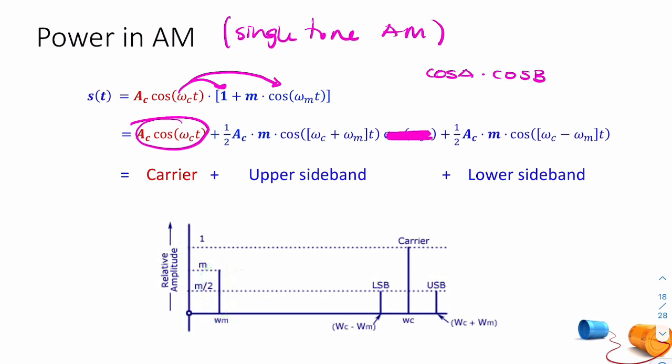And this is your original message. So this is m of t, or M of omega. This is your original message, but it doesn't exist at the same time as your bandpass signal. I've included it, and you'll often find this in textbooks, included on the same axis, but they don't exist at the same time. Why? Because this is your bandpass signal. This is what you actually broadcast, whereas this is your baseband signal. So let's just put that dotted, because it doesn't really exist. It's only there to show you that a very low frequency has been shifted up to a very high frequency. That could be in tens of kiloradians per second, and here you'd have hundreds of kiloradians per second, because omega c will be 50 to 100 times omega m.